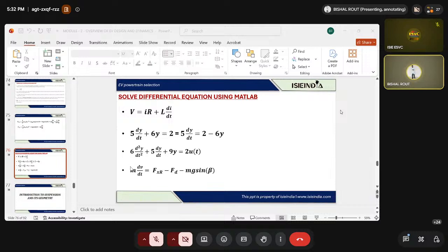Now I have a question, sir, whether the drag coefficient is publicly available. I will say no, it is not available publicly, because if it were available publicly, you could design a specific vehicle around it. So it is not publicly available, but you can take it randomly. AF is given as 2.19 meters square. The density of air is 1.127, which is constant.